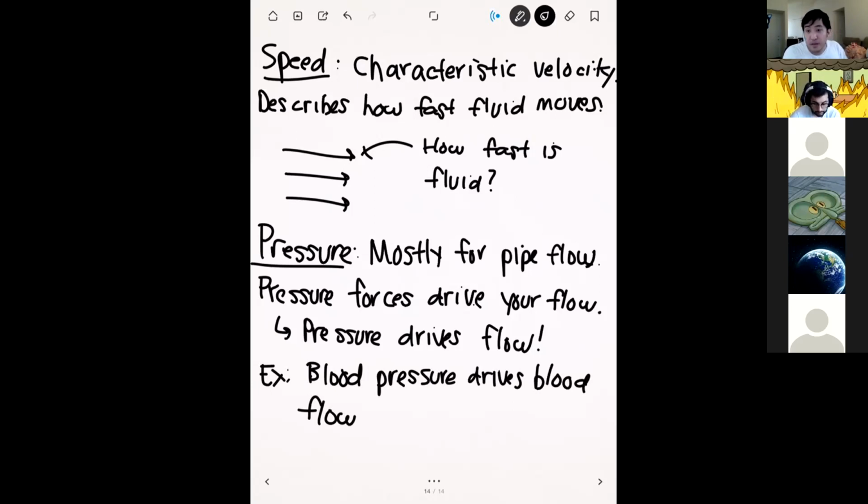All right, so a question: does that mean there is more flow at the bottom of a dam? No. One thing we'll learn in a few weeks is that fluids conserve mass. Whenever a certain amount of fluid comes into a system, that exact same amount has to come out, assuming steady conditions. If it's unsteady, you can have more flow coming in and out, or vice versa. But we'll be mostly dealing with steady situations. So any fluid that comes in has to come out in the exact same amounts, because mass can't be created or destroyed.